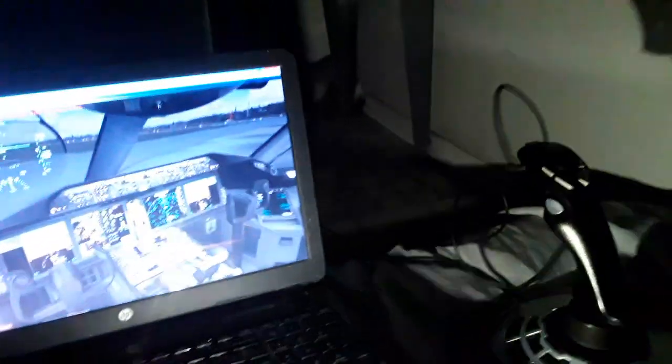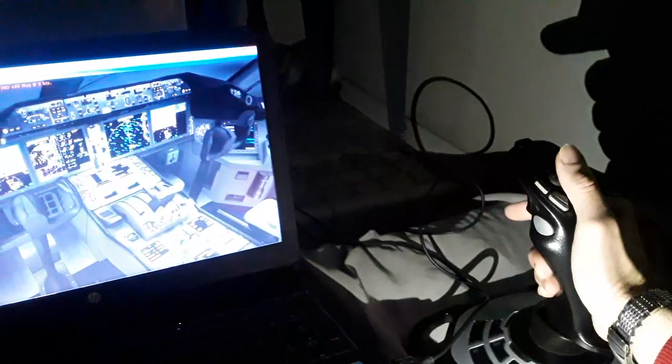The pressurizer from the engine 5th and 9th stage, and also the bypasser compressor from the bypass stage. So we have pressurizer from the engines is applied for hydraulic fluid tanks pressurization. So we need all the flight controls you see here. Need hydraulic fluid to move around.